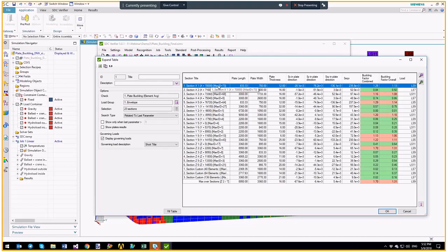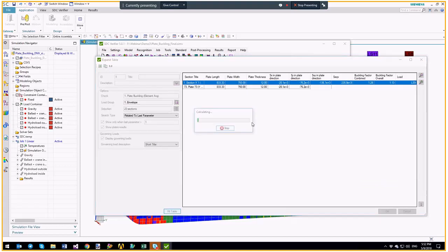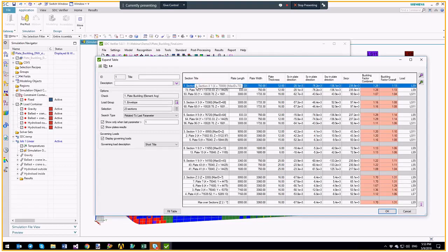So it's basically a summary. If we want to go into details, we also have some options here to say show plate results and show only the plates which fail. I will do that in a moment. So for example, in frame 1 I have 2 plates which fail, with results above 1. So here we configure this with this option.